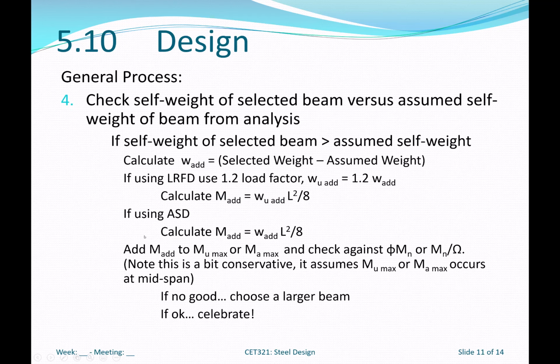Okay. Now, the last tidbit of check here is the self-weight. If I had to assume a self-weight, is it adequate? Is the self-weight maybe specified in PSF also adequate? So we want to make sure that the dead load that we included in our design is adequate.